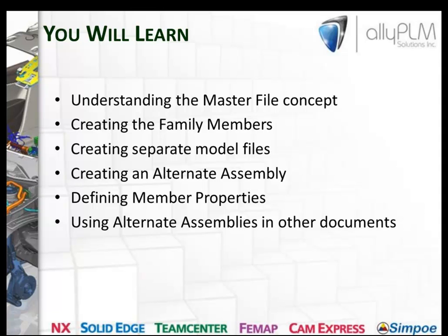Okay, so like I said, we're going to look at family of parts and family of assemblies. Some of the things we're going to look at is the concept of the master file, how to create family members, how to create separate model files, how to create alternate assemblies, define member properties, and use alternate assemblies inside of other documents like assemblies and drawings.